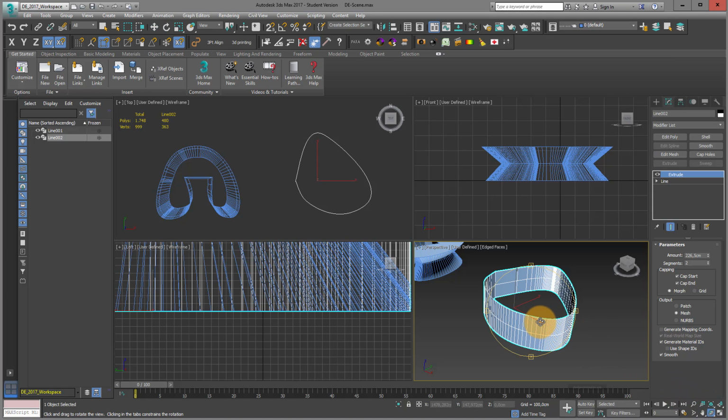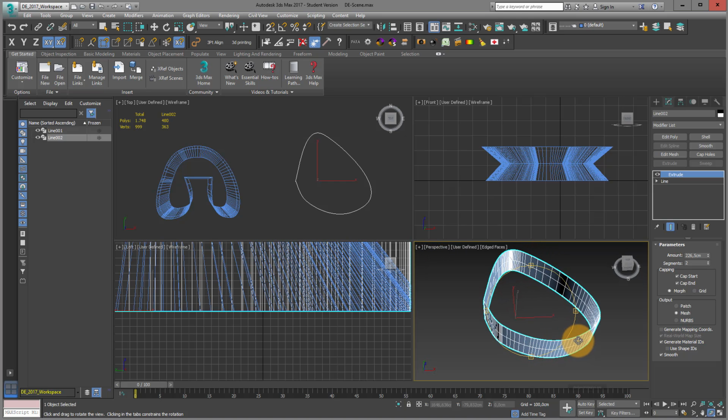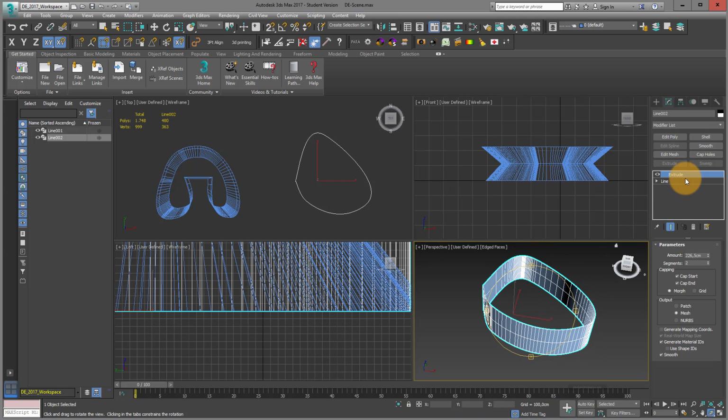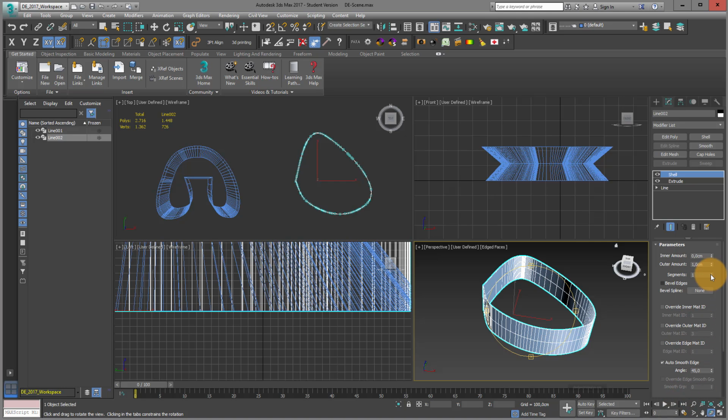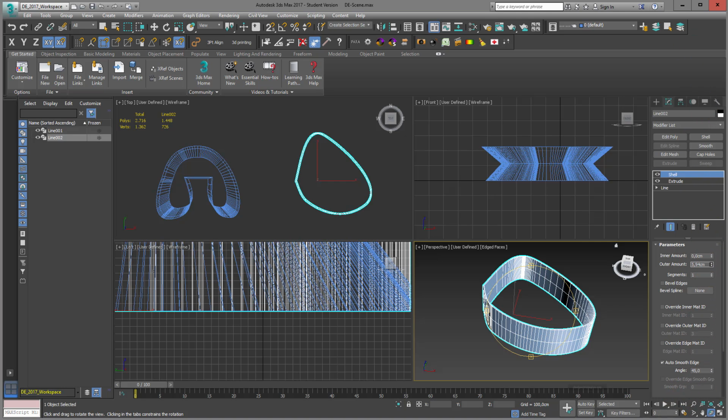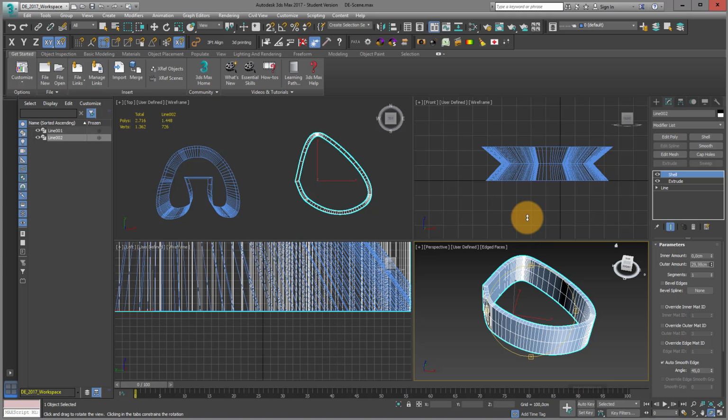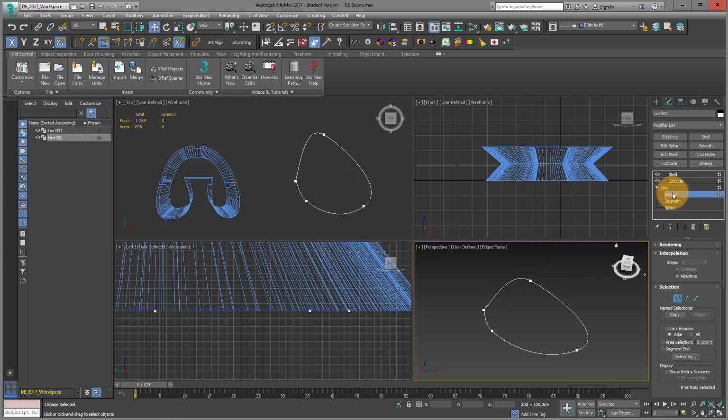If you have this wall, you can put something like a shell on this wall and give this whole thing a dimension. That's definitely a common method. But if you want this also to be a closed spline, you can just go into the hierarchy of the lines and select all your vertex points, Ctrl A, or actually you know that it's about these 2 points.